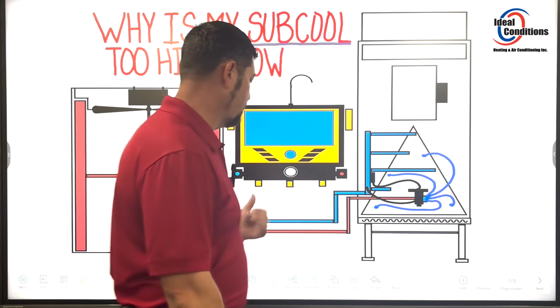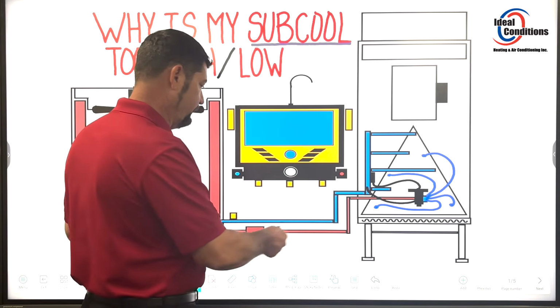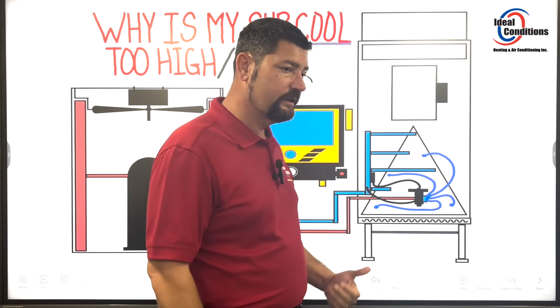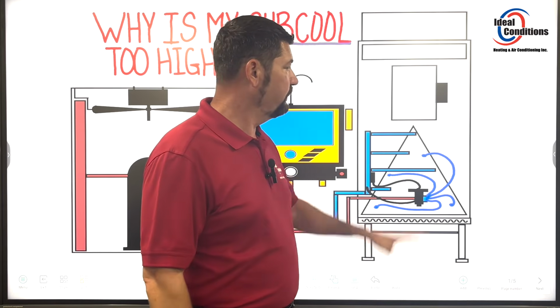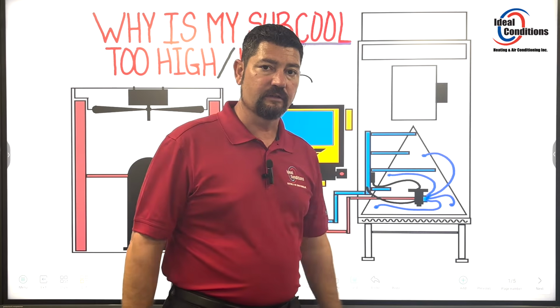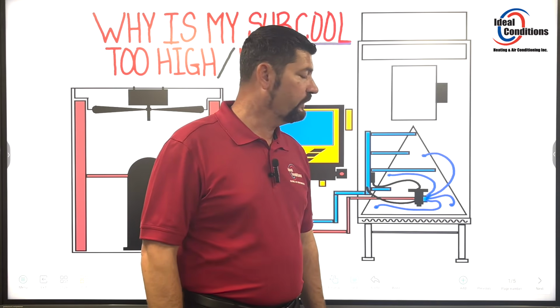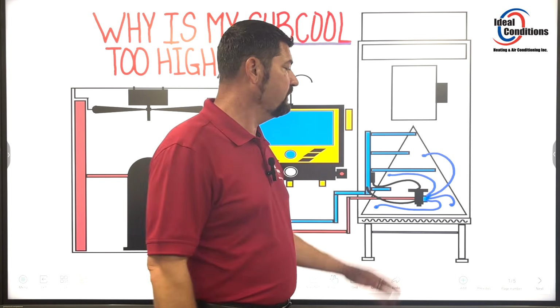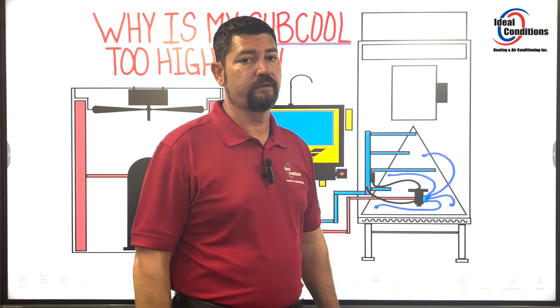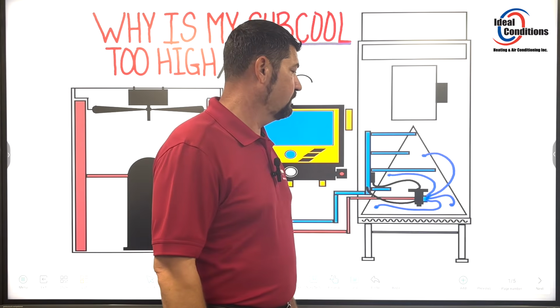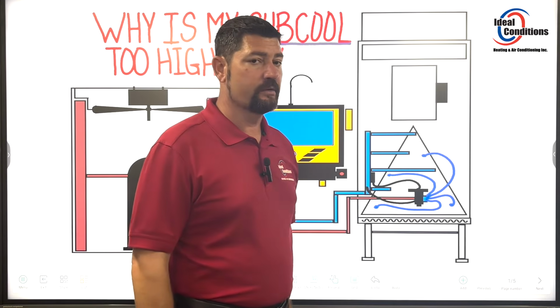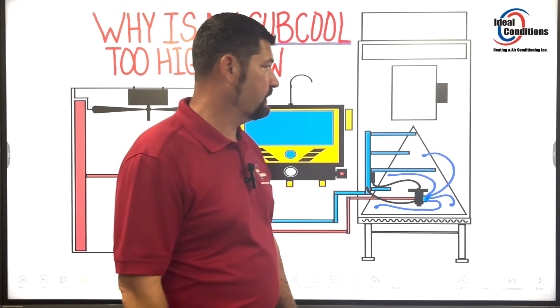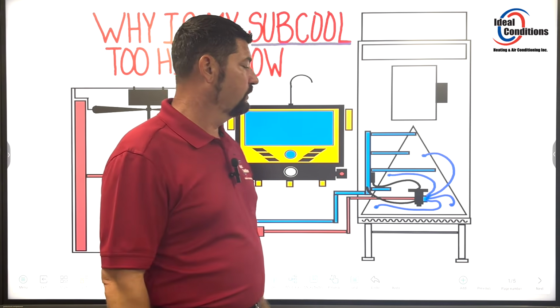And so somebody's going to come behind you. They're going to be sitting there going, "Man, I'm trying to get the superheat and the subcool just right. I just can't." Well, that's because 1 + 1 can't equal 2, because that's already been changed. They put a 5-ton blower on it and set it for high speed on a 4-ton application. You're moving 600 CFMs of air, which is 1.5 tons of airflow more than the evaporator coil was designed to have. And on top of that, you also now are going to kill that motor because you have excess static pressure because the ductwork wasn't designed for it.